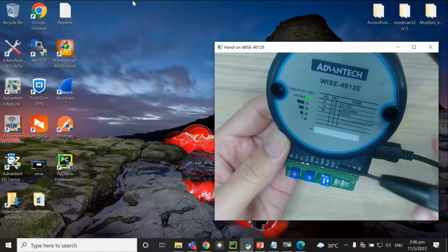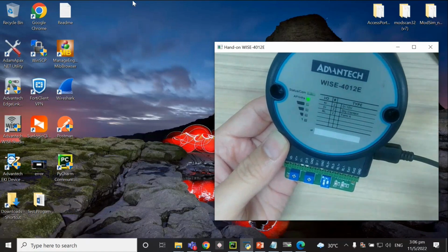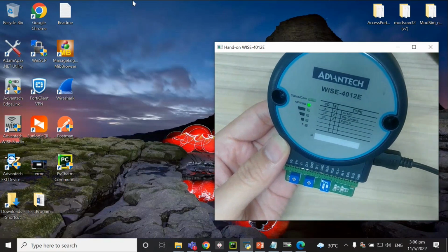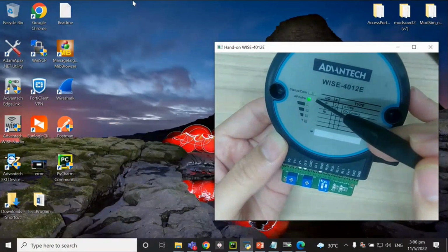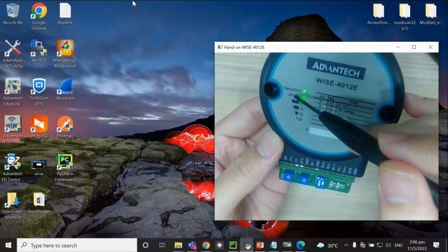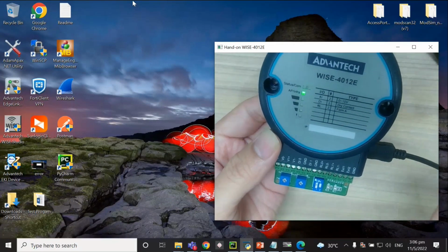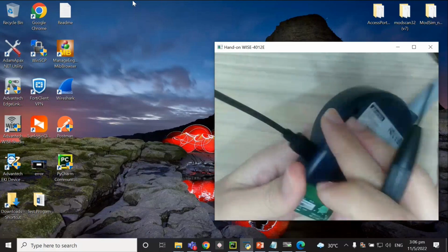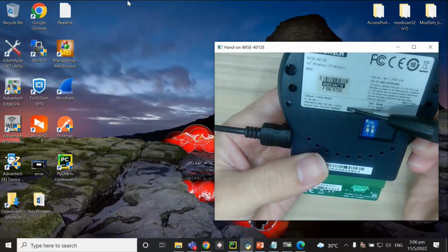What's the difference? Previously, you saw the signal bar there. Actually, the signal bar means the normal mode. If you see the signal bar, you are running in the normal mode, with the actual application running. But for the AP mode, infrastructure mode, you will see that this LED will be on. So when you set your device to the initial mode, you have to use the device IP address. This is exactly the same as what they label at the back side.